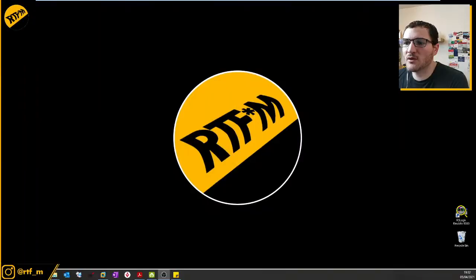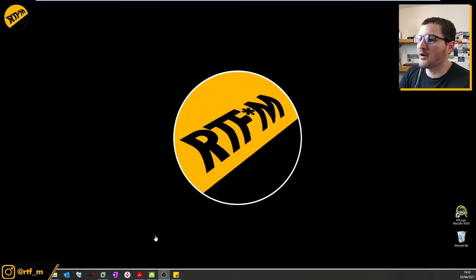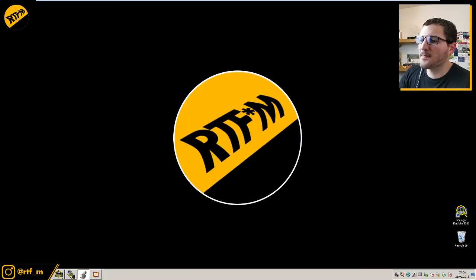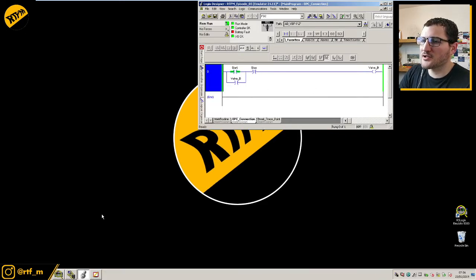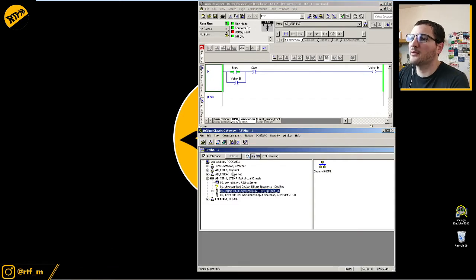All right, so without further ado, let's dive into how to configure your emulated controller to a FactoryTalk View project using OPC. Let me just switch screens, so it's easy for you to see. Here we go. We've got our logic here, our code running from our previous video. It's simple logic with a start and stop button, and now a valve, which I called valve B. First things first, I'm online.